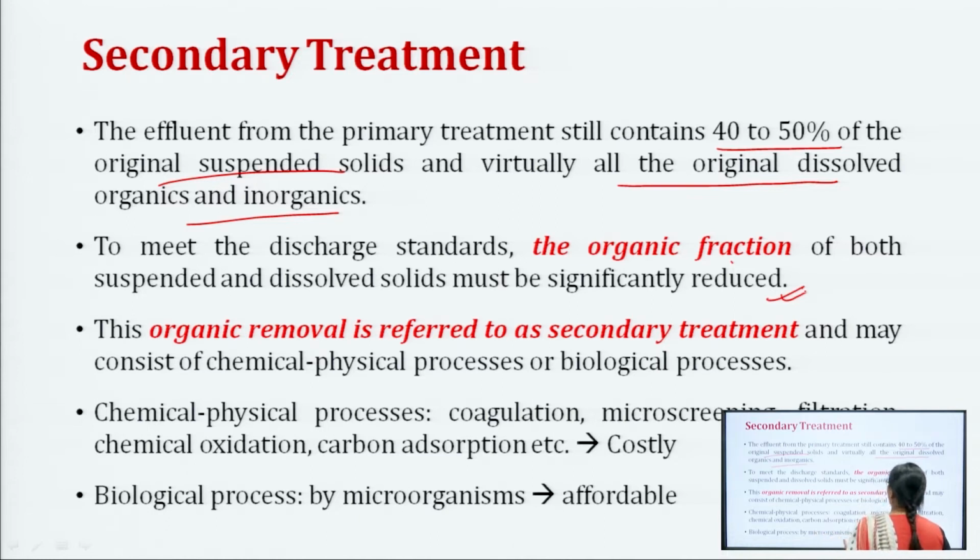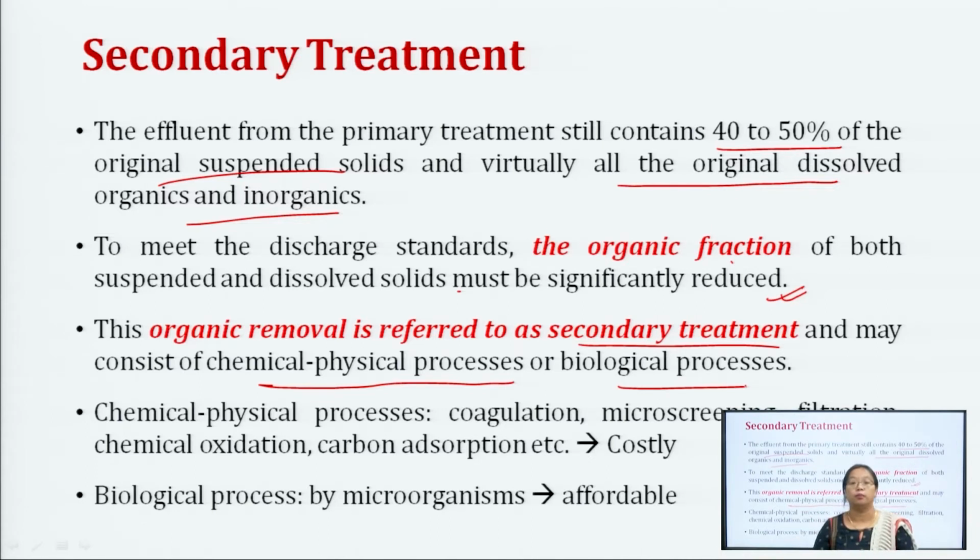So, what you have to do is remove the organic fraction of both the suspended and the dissolved solids. This organic removal is referred to as secondary treatment, and may consist of chemical physical processes or biological processes. Secondary treatment comes after the plain sedimentation. It is supposed to remove most of the organic fraction, and it consists of either chemical or physical processes or biological processes.